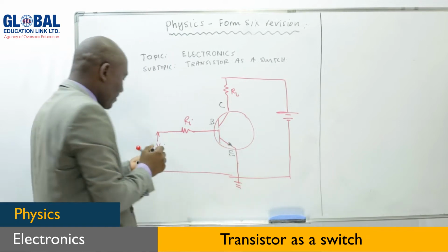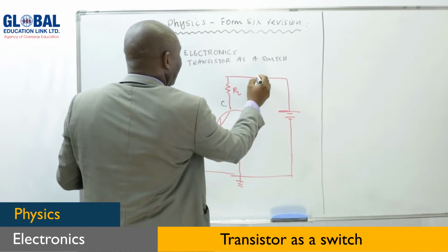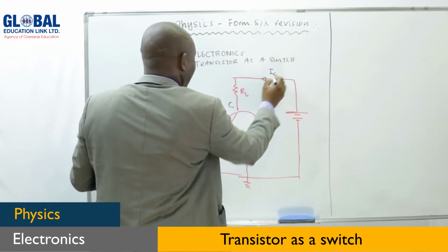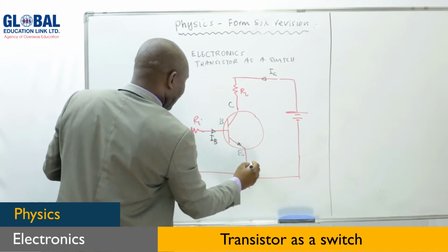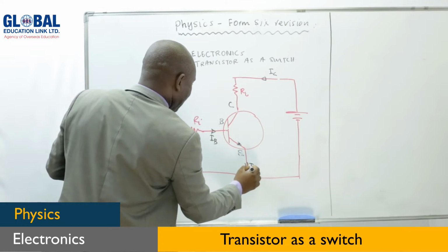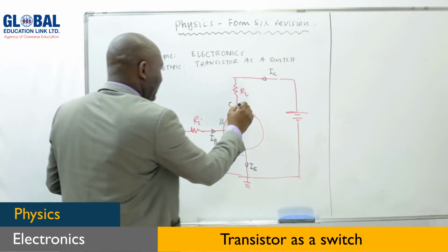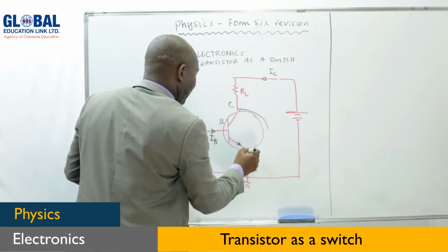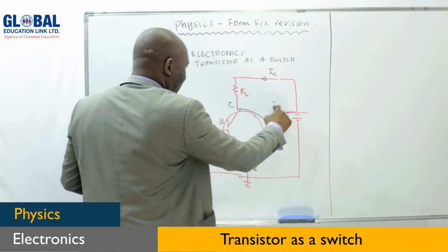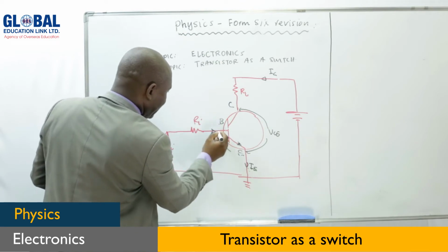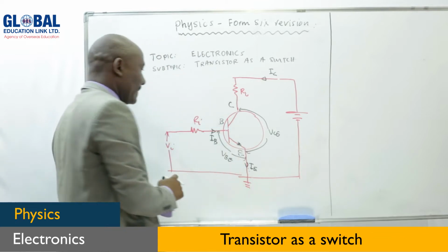Let's consider that we are talking about the NPN transistor, such that here we have the base, so the collector current is produced by the base. And then we have the emitter current. You remember this is the common emitter arrangement. And this voltage here, if you remember, is the voltage across VCE. Of course, it's taken from here. That's where we have the output. This is the voltage across the junction, which is given as VBE.